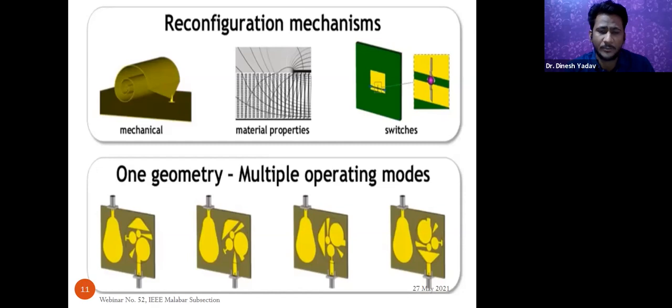Below that, you can see different antennas mounted on a single plane. There is a bulb type of antenna connected with a coaxial connector, which is the supply. If we feed the energy from here, it will provide a fixed radiation. Whereas here, all the antennas are fixed on a rotating surface. So one time this antenna is connected with the feed, the second time this triangular shape, and then a small circular antenna and triangular shape antennas. So this reconfigurability is produced by mechanically moving the antenna surface.